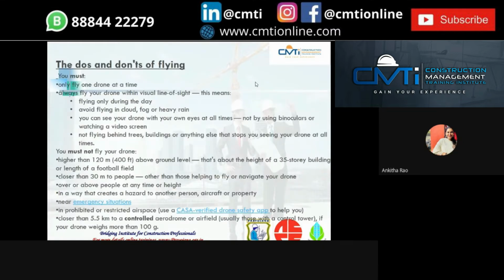Okay, these are the do's and don'ts of flying. You can fly only one drone at a time, and it should always be in your visual line of sight. That means flying only during the day, avoiding flying in cloud, fog, or heavy rain. You can see your drone with your own eyes at all times, not using binoculars or watching a video screen. The drone should be visible to your bare eyes, and not flying between trains, buildings, or anything else that may cause any damage.